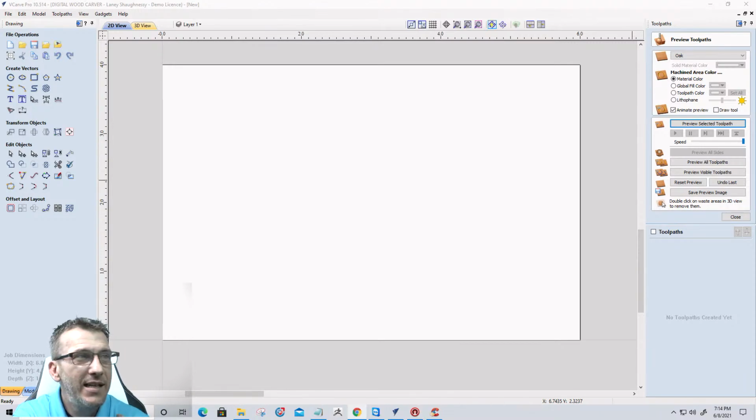But yeah, this is a great project, by the way, guys and girls, for scrap woods. If you have little blocks of scrap and you don't know what to do with it, these little boxes are an awesome fallback project. They can be made out of 3/4 inch material, but as far as holding capacity, it would be better if they were around 1 1/4, maybe 1.5 inch deep boxes. But absolutely, you can make them in different thicknesses. You know, 3/4, 1 inch, 1 1/4, 1.5. Anything less than 3/4, it's not really feasible for a box.